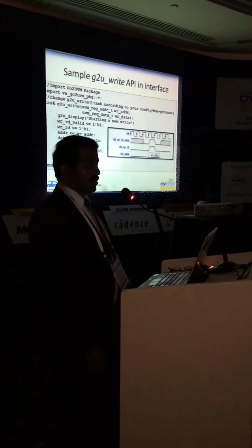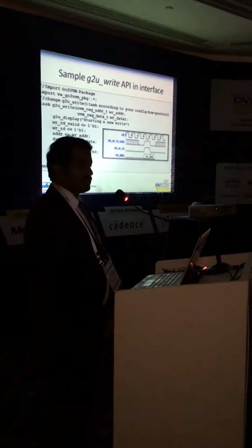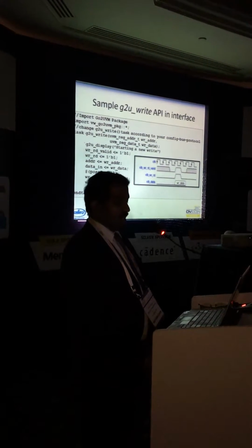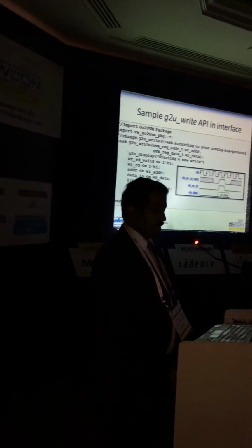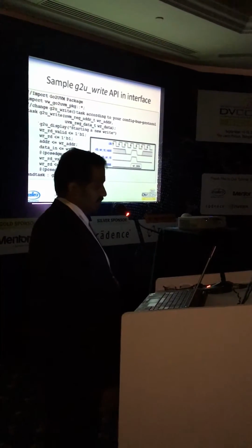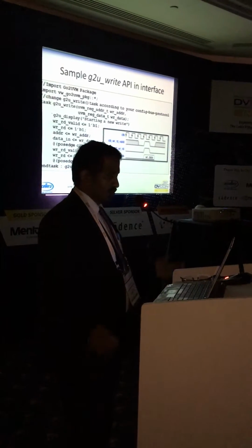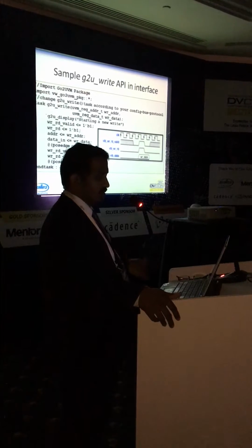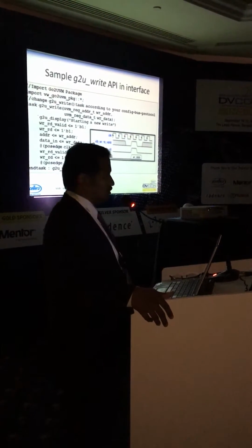Let's look at two slides, a little bit crowded. Let's assume that you have this timing diagram that I was talking about. Similar to the waveform, you have a small protocol that says, if I were to do a write, put the write read signal high and then write read valid high. And my claim here is any Verilog engineer could write the code over there. You do not have to be a UVM expert. You do not need to understand OOP to write this code. You could say, okay, write read is 1, write read valid is 1, put the address, put the data, wait for a clock, pull them down, and then we are done. That's all we are asking: fill it into GTU write.